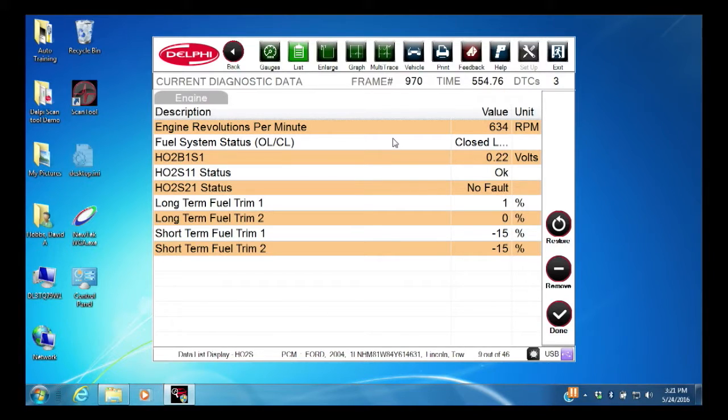In this case, we are showing negative fuel trim numbers, indicating that the O2 is higher than normal. As you see, it's kind of hanging out mostly in the higher numbers, 0.7, 0.8, and so forth, occasionally going lean, trying to make the switch, trying to do fuel control, but negative 16 to 18 on the short term, that's definitely indicating a rich mixture.